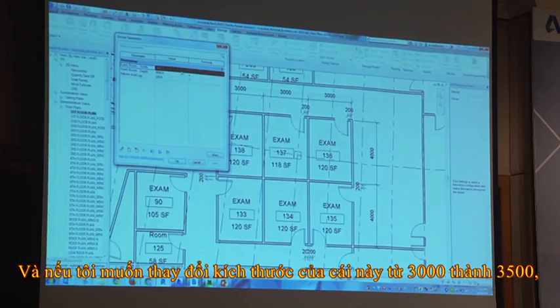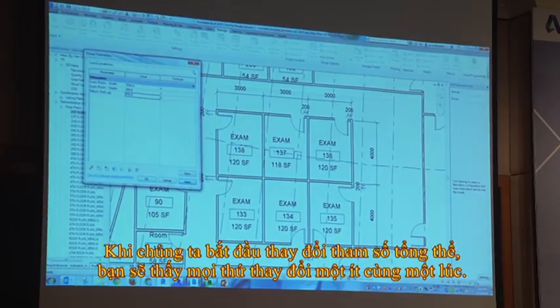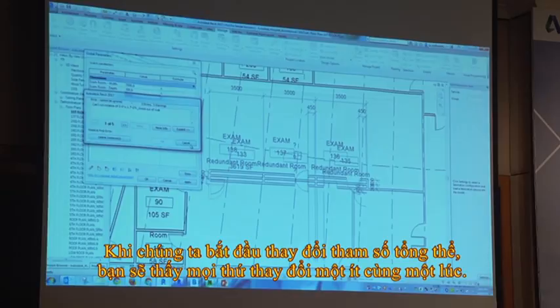To saying that, hey, I want to change the dimension on this one from 3000 to 3005, depth from 4000 back to 3000, all right? And the return wall length, I'm going to make a very huge gap over here so that you guys can see the difference. So when I start to change the global parameters, you can see everything is going to be changed at the same time.